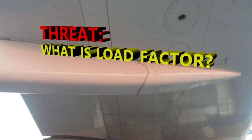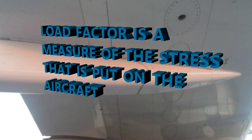The next thing is load factor. A load factor is basically a ratio of the lift of the aircraft to the weight of the aircraft. It is a measure of the stress that's put on the aircraft.